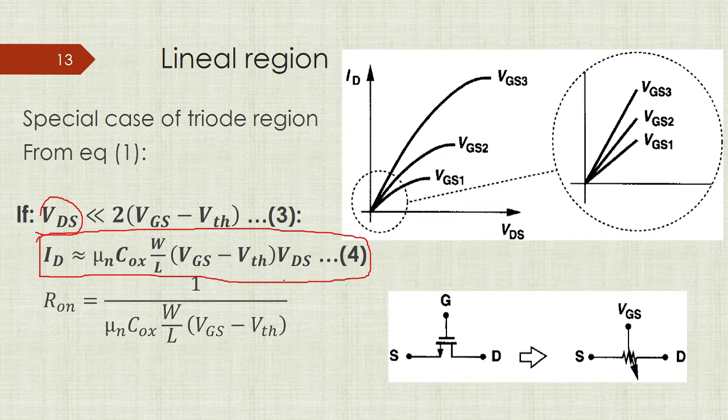If you see here, we have VDS, the current that flows through those terminals, and a constant in between. So this is similar to the resistance relationship. In a resistance, we have a linear relationship between the current and the voltage. If we move ID to the second part of the equation, we can obtain the resistance of this transistor.